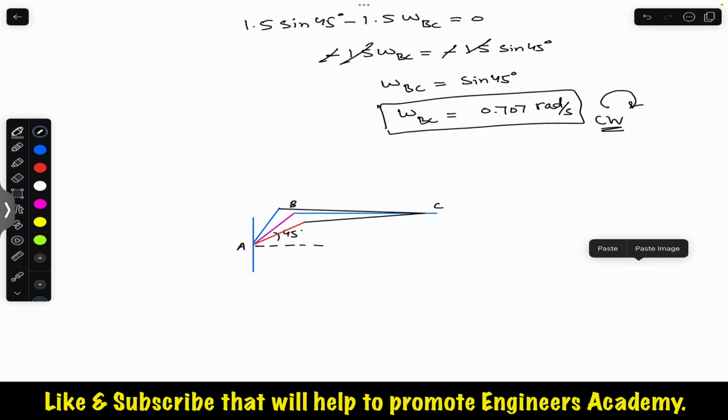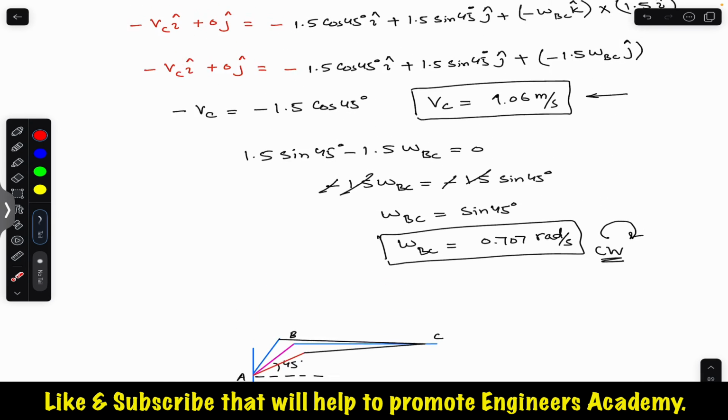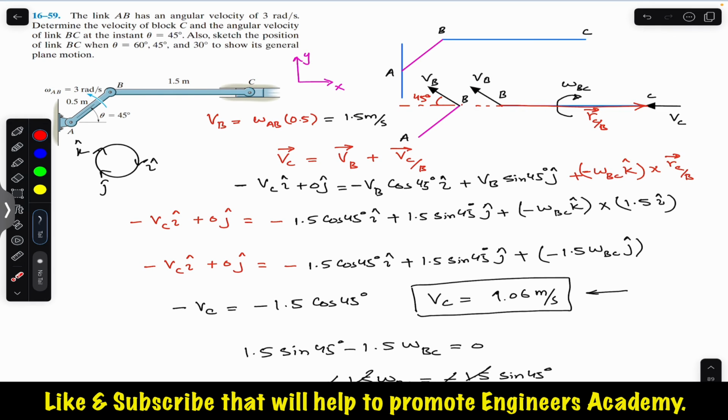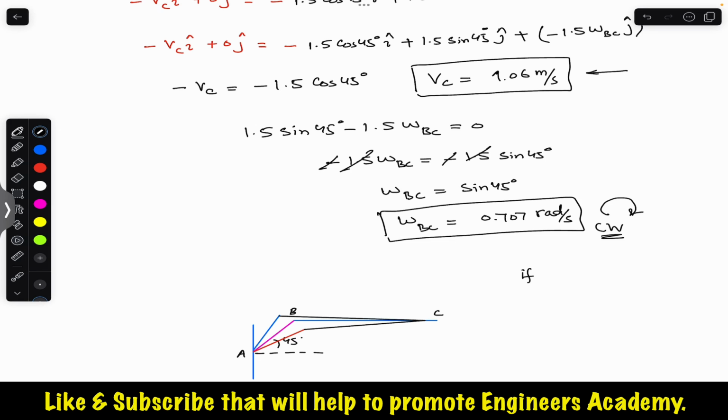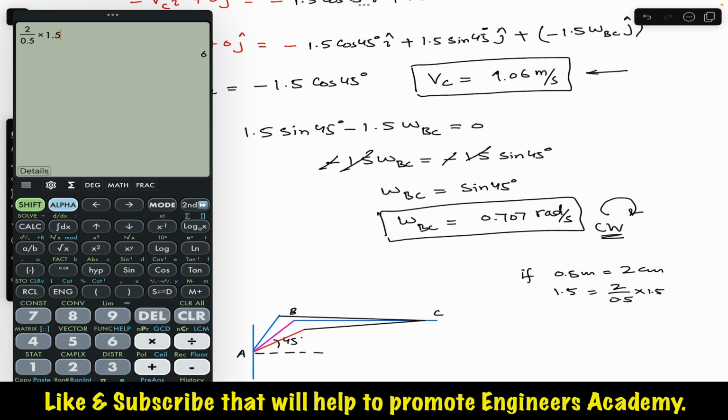But if you want to draw the accurate diagram, then you need to select a scale, and then according to the scale, draw a length AB of 0.5 meters. Let's say that 2 centimeters is 0.5 meters, so then 1.5 will be 2 divided by 0.5 into 1.5, which is 6 centimeters.